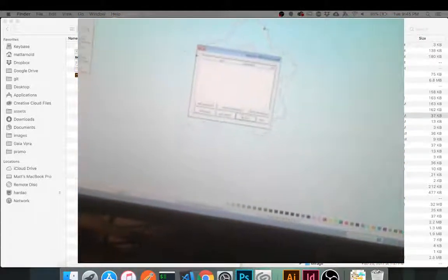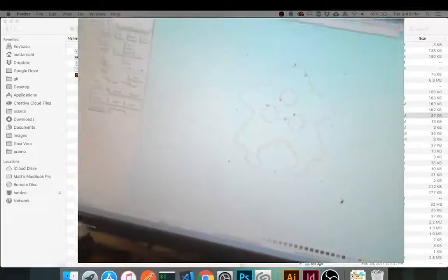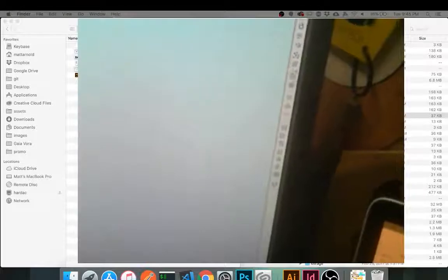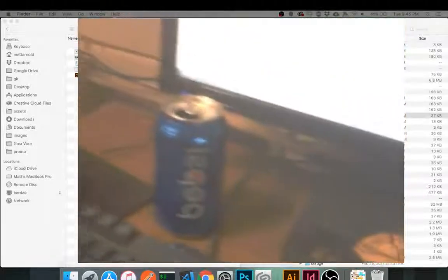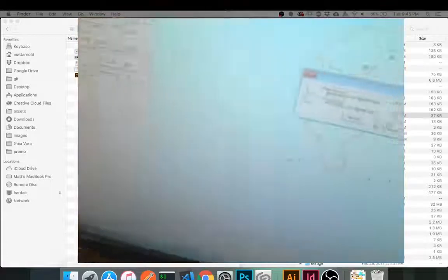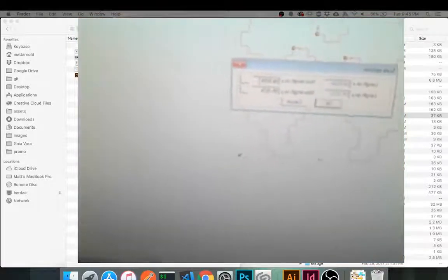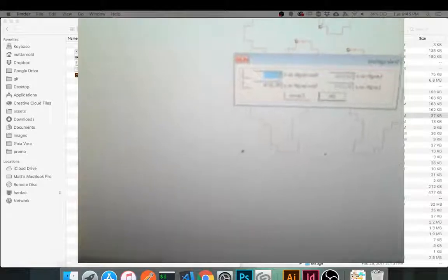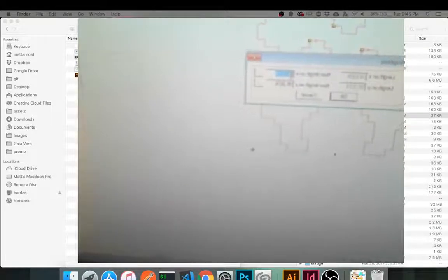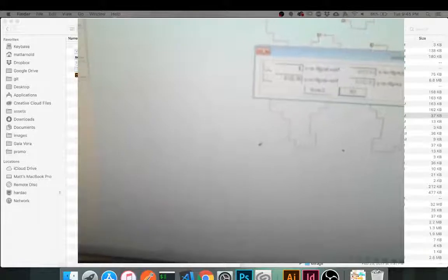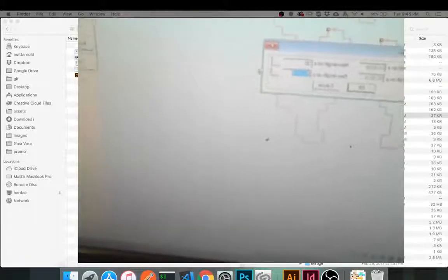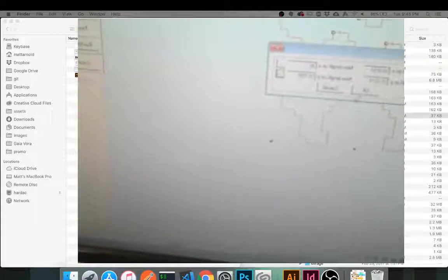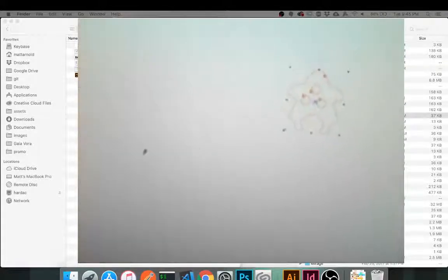So I'm going to go back here, and I'm just going to select this and delete it from the laser. I'm going to grab this and use the scale tool, which is right here, and put in a different number of millimeters. Let's say 30 millimeters instead of 84. And now click that. So that shrank it down.